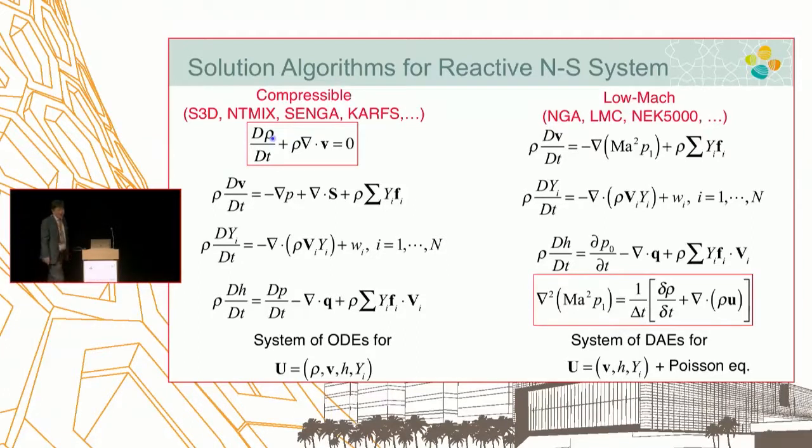If that were the case, how could we possibly do incompressible simulation for air, whose density can change a lot? It is all about the Mach number, and again, unfortunately, I don't have enough time to talk about that. That way, the pressure is decoupled into thermodynamic and hydrodynamic components, and it is only the hydrodynamic component of the pressure, which is of order Mach number squared, a small variation, that we keep. And that is the one driving the flow field of the subsonic flow. That pressure needs to be determined now that we decouple density from it. So we solve it with a steady Poisson equation.